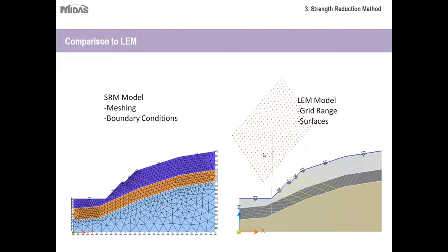And what the program will do is it'll take each of these points here and link it up to a tangent or a point on that failure surface, and it'll create a series of slices for it and the factor of safety. So as you can see, it's something that would be very repetitive done by hand, but the program does all of it very quickly. Within a matter of seconds, actually, the calculations are done.